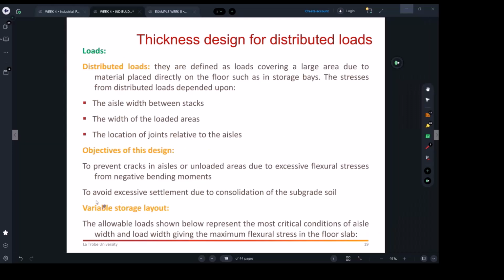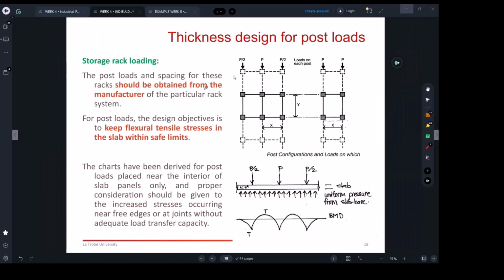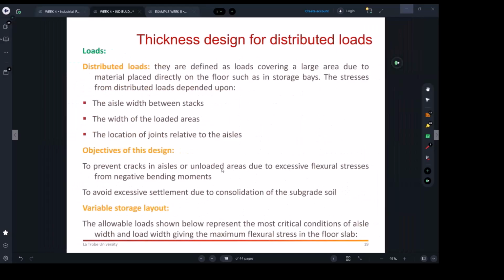in the slab. And again, same thing, the CBR and that question I showed you to do with the subgrade as well. So why we need to be careful in all those distributions and the load and the dimensions and the spacing is basically to make sure the concrete slab won't be overstressed in terms of tension and get cracked.